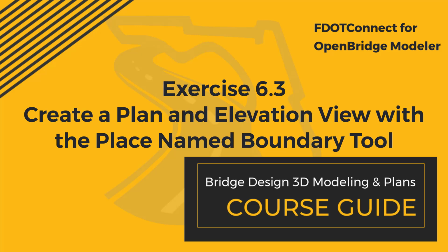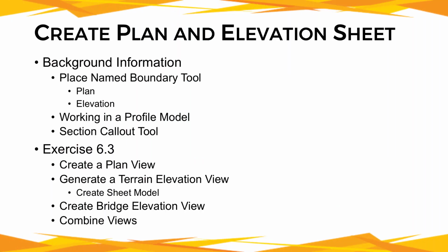Let's get started. Now in this video, we're going to start with a little background information on the tools it takes to go about creating the plan and elevation sheet. We'll first touch on the Place Named Boundary tool and discuss working with the plan and elevation named boundaries. Then we will touch on working with the profile model and using the section callout tool and how that will be used in this process.